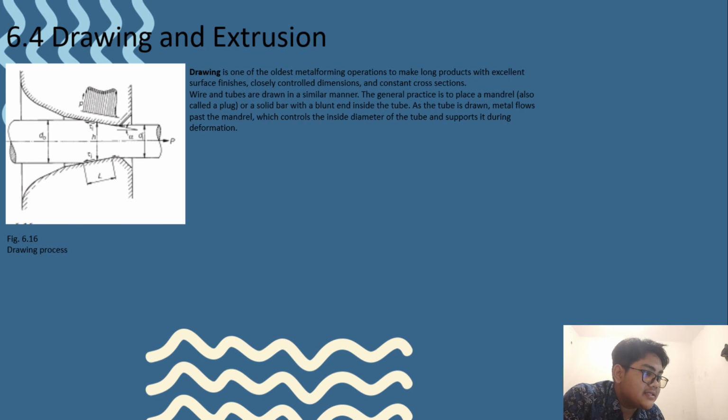Practically all metals can be extruded, although the capability of many alloys to be processed in this manner falls within a narrow range of processing conditions that depend on a variety of application-specific factors. Special techniques to extrude different materials are to a large extent dependent on the extrusion temperature and room temperature. Cold extrusion is economically feasible for low melting alloys and some aluminum alloys, while hot extrusion is required for harder alloys.